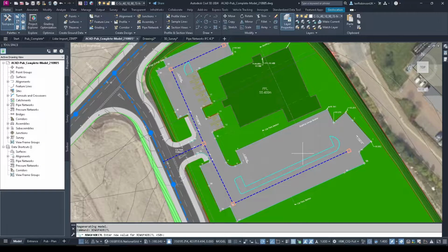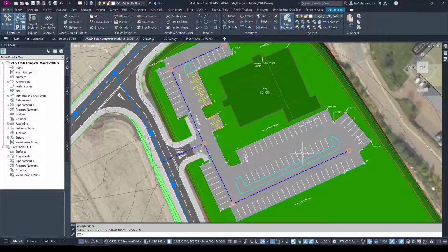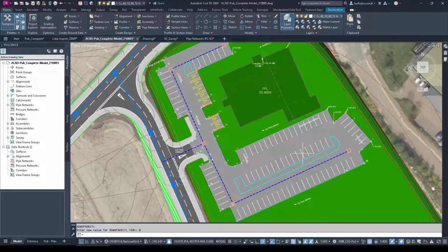There it is. And that controls how much it's faded. If I go to 90, it's faded in one way. If I go to 0, it's totally not faded. If I set it to 50, it's half faded. So you've got the different fade controls. But note, that's a system variable. So if I change it to 0 now, it will be in every drawing from now on. I will not have any fade on any xrefs. But again, that could help with performance because you're not having to insert stuff.